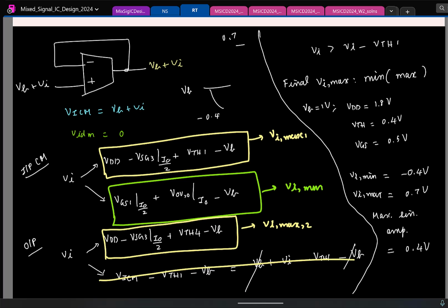Okay, so I can only do this, and I can't use this portion. Right? You are saying that you can shift this offset here, but that will essentially mean you are changing VB. So which means the numbers will again change. Right? So yeah, as I was saying, this is basically the swing limits that we have been working out. Just that for op amps, this is how we compute. Okay.